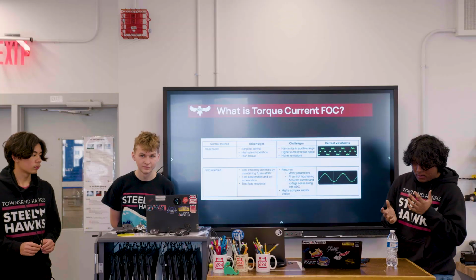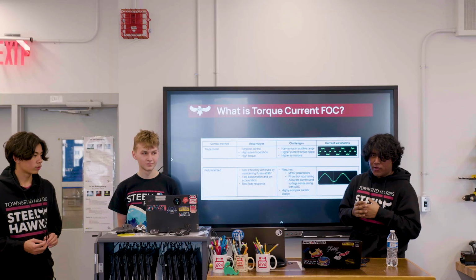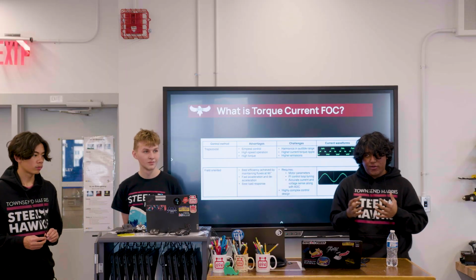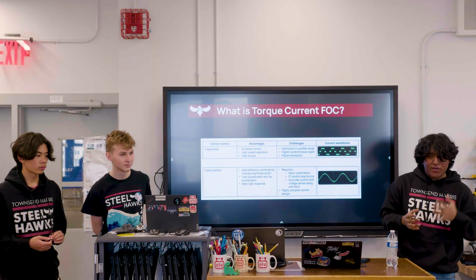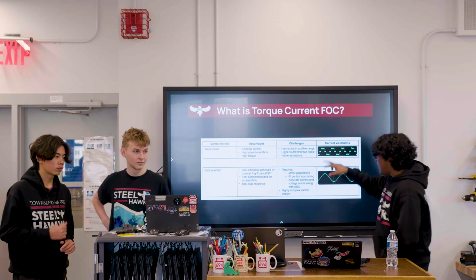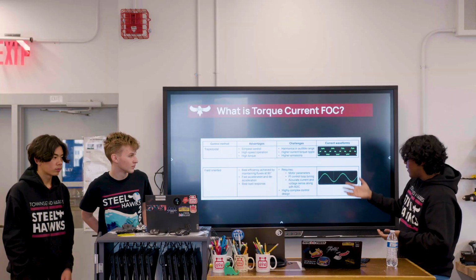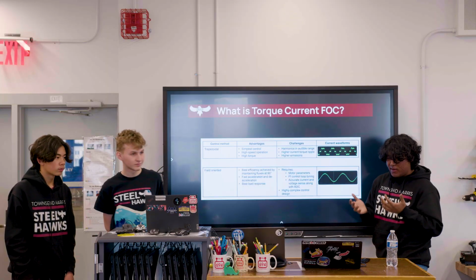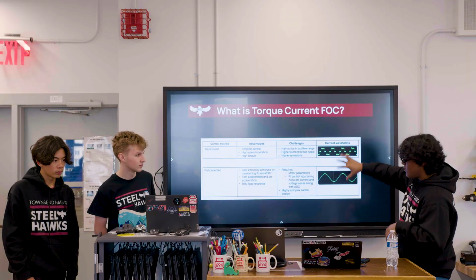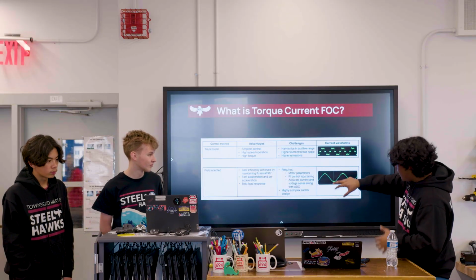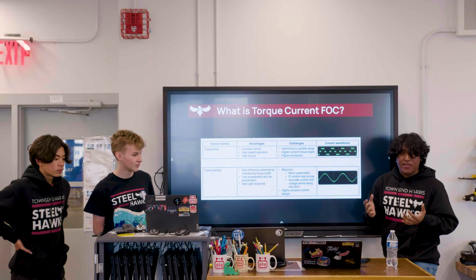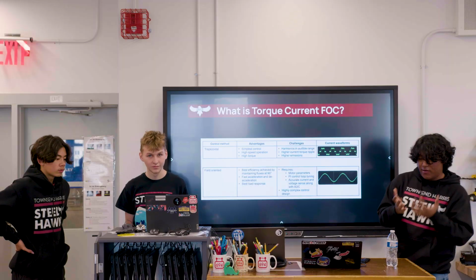While in FRC our motors are so robust that it doesn't really matter, because of these torque ripples you're still leaving performance on the table, because your torque will go up and then drop for a moment and then go up. You can see here it's not as continuous as this one. Because of that, you're losing acceleration every time you go over one of these humps. Because this is a continuous function, that's the main reason why you have so much extra acceleration.